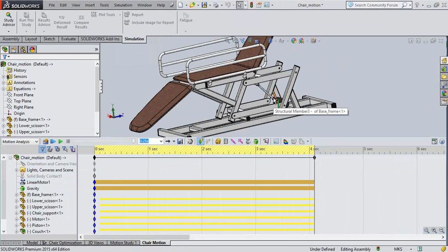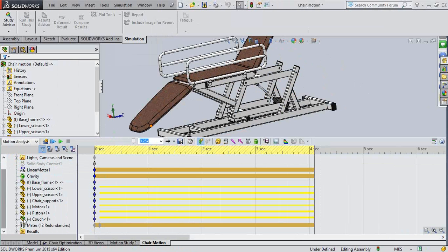So my SolidWorks Motion basically works with the mates. So you have to be definitely aware of using the mates. It totally works on how the mates are given in your assembly. But then you can give some local mates in your motion study as well. If you are not working out with the mates in the assembly, you can play with the mates within your motion tab as well.